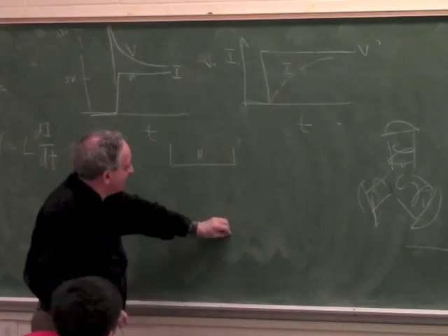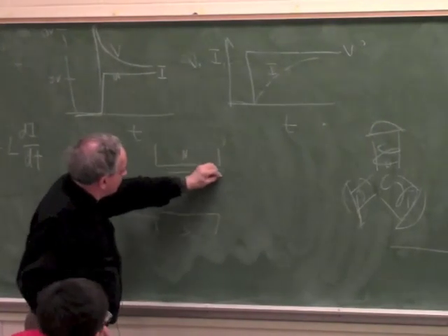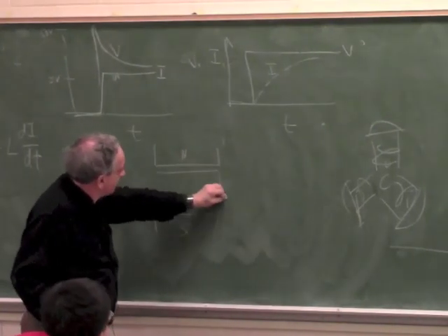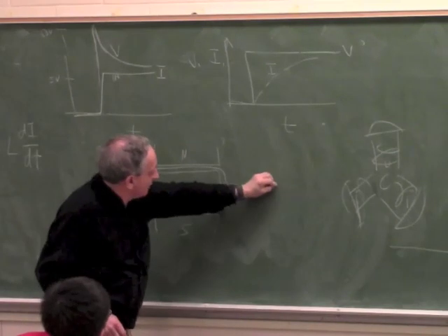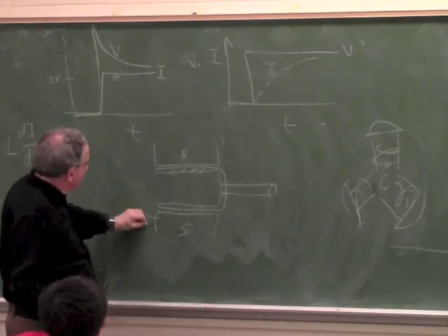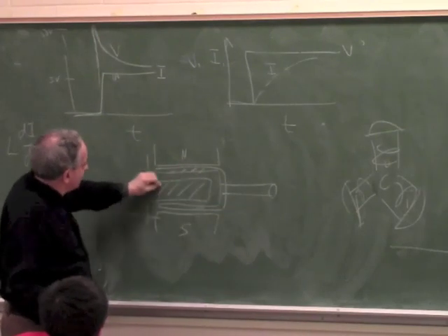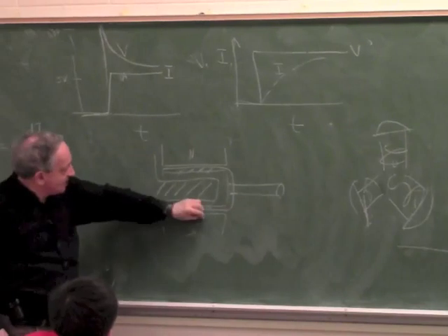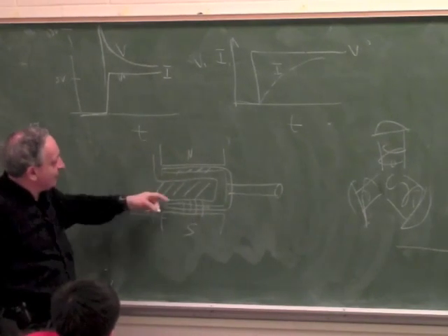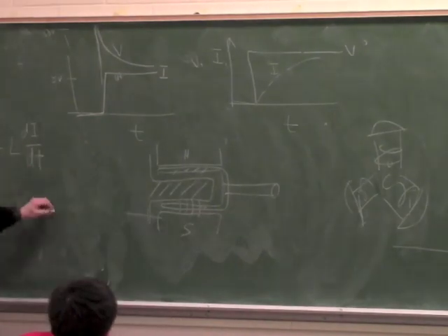So the way they work, you have a magnet in cross section. You have a magnet, NS. Now you have a coil which looks like a cup connected to a shaft. So this thing is a winding, and then you have a piece of steel inside. So what happens, the flux still has a small air gap, but the piece of steel doesn't rotate, only the cup rotates.